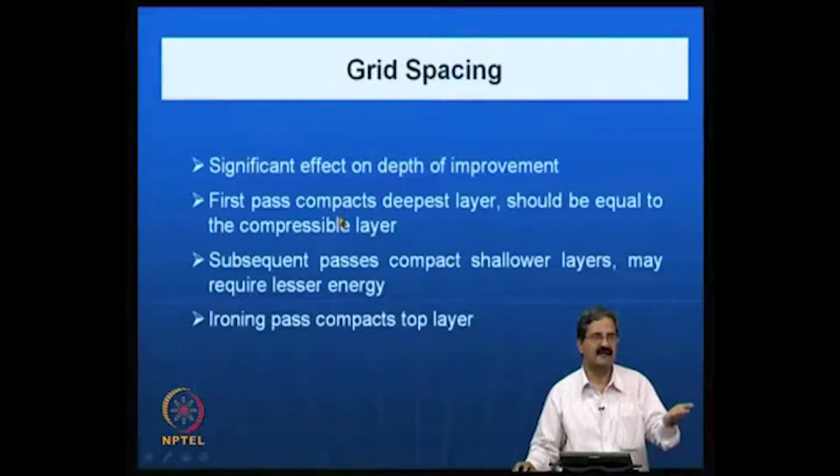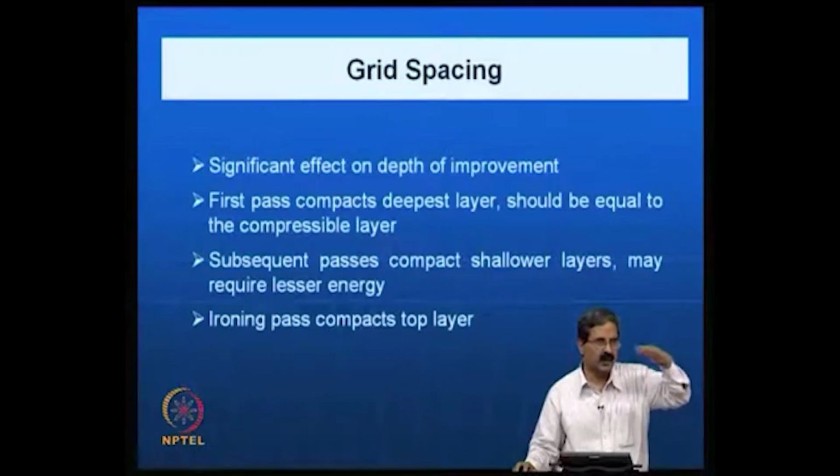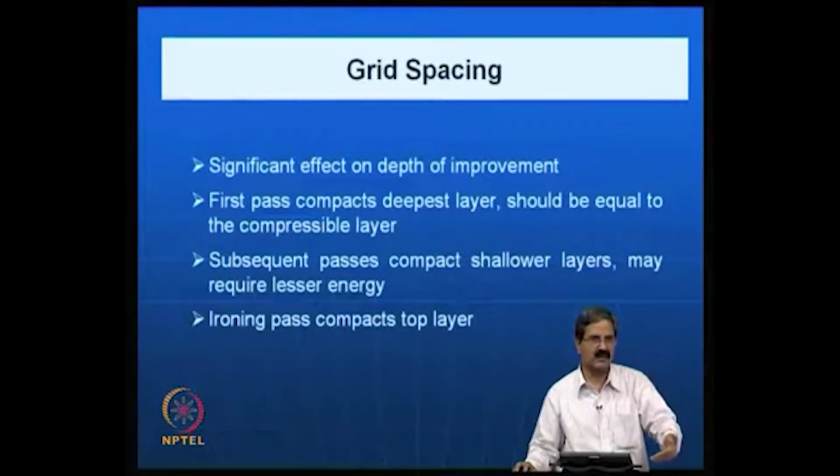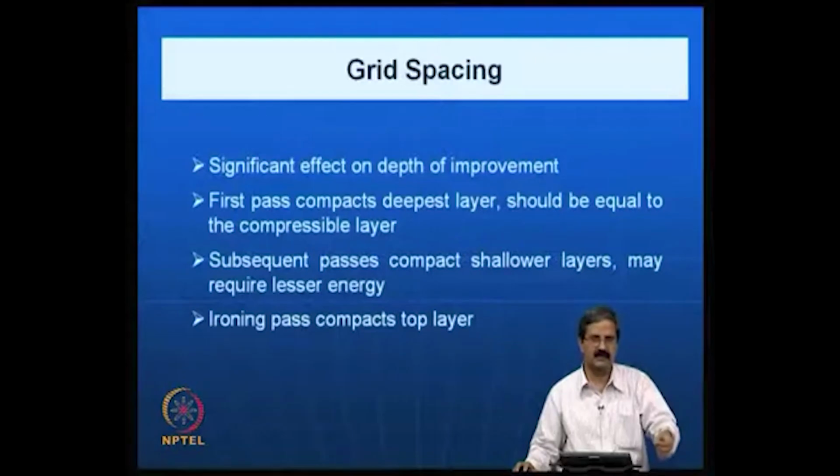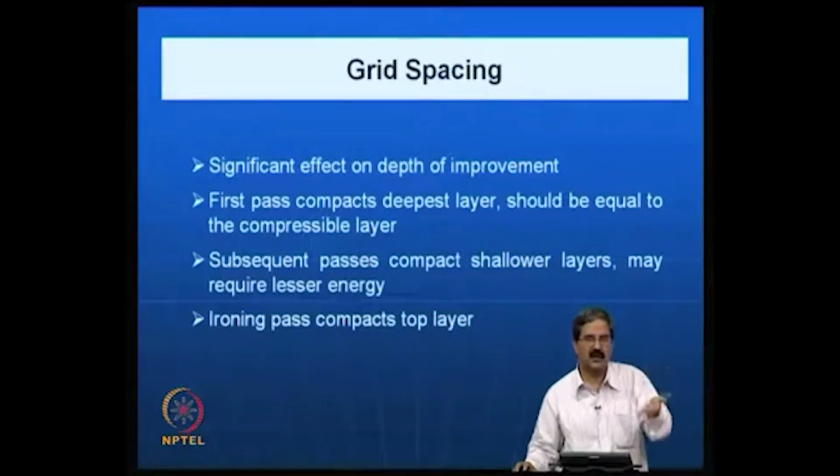You should be able to do some sort of analysis where you have a soft soil area, you construct all the buildings there, and then ask what load is getting transferred to what point. Suppose I assume that the soil is soft, up to which point are the stresses going? Suppose I compact very well and make all this very strong, the stresses will not go deep.